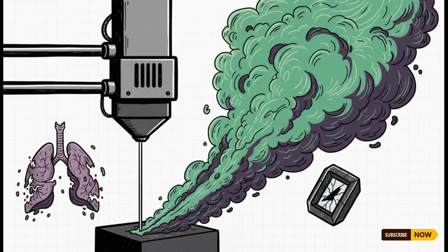Yes, the exact same gas used historically as a deadly chemical weapon. This gas will rapidly corrode and destroy the expensive linear rails, optics, and electronics inside the laser cutter. But much, much worse, it will violently ruin your respiratory system. Material Safety Data Sheets, or SDS, exist for a very good reason. You must know exactly what chemical compounds you are vaporizing before you ever fire that laser.